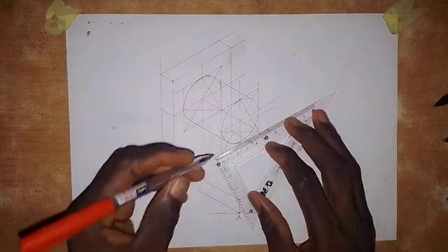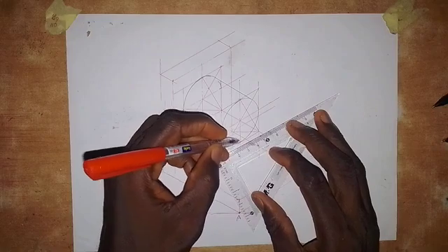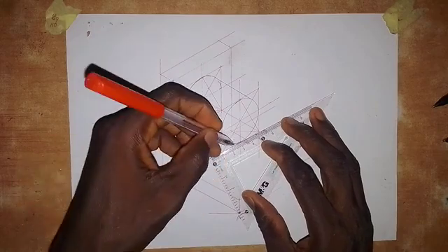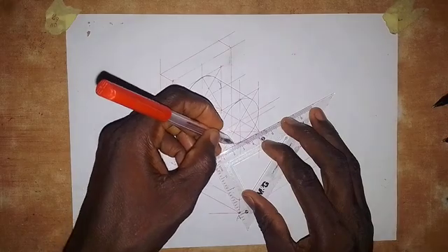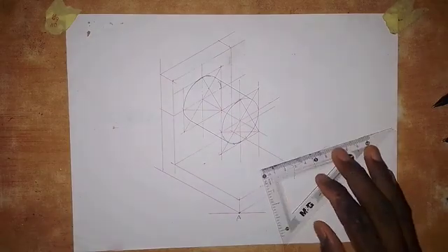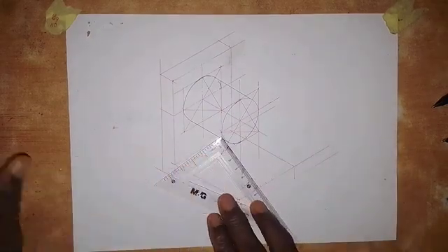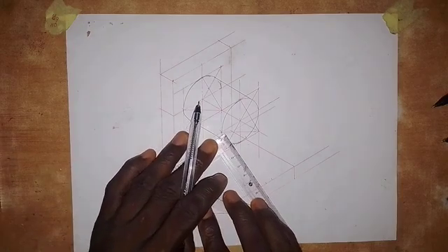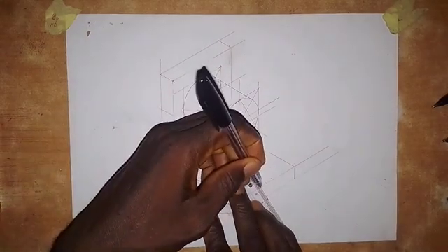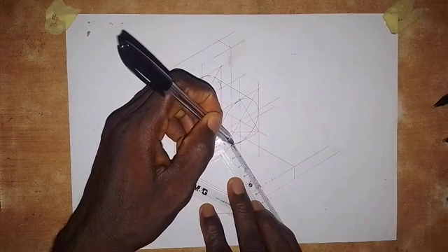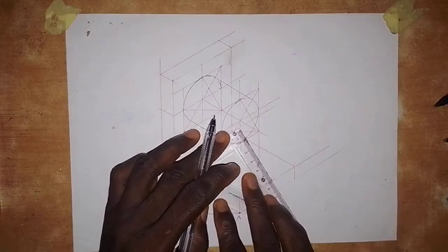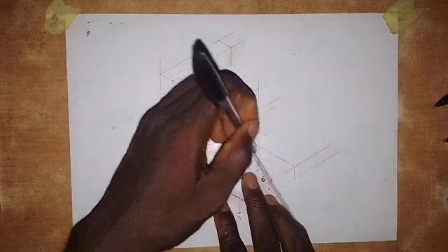Having done that, the next thing is that we come onto the center of the cylinder, this midpoint here, which we already have. We take 6 millimeters to the left side and 6 millimeters to the right side here. So we have this. We are going to connect these points together. I will use my black pen at once. Connecting these 2 points together, it goes like this. This is a non-isometric line. And then we connect these 2 points together. So it goes like this.